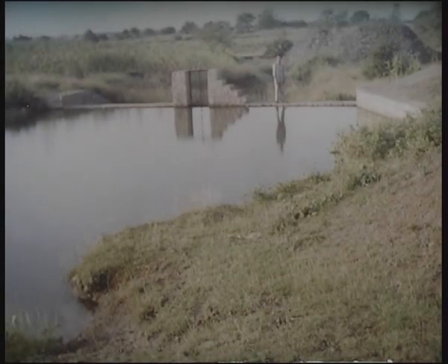That is because the upland areas continue to have very deep water table levels, and the benefit that is caused by a structure in the main stream is actually increasing the groundwater availability in an area in the valley which is already favored with good groundwater. So therefore, it is necessary to have a revised technology with regard to recharge structures, giving emphasis on increasing the water spread area.